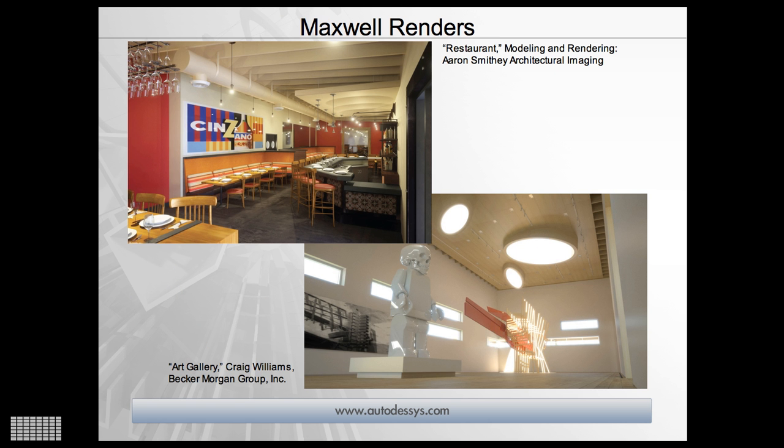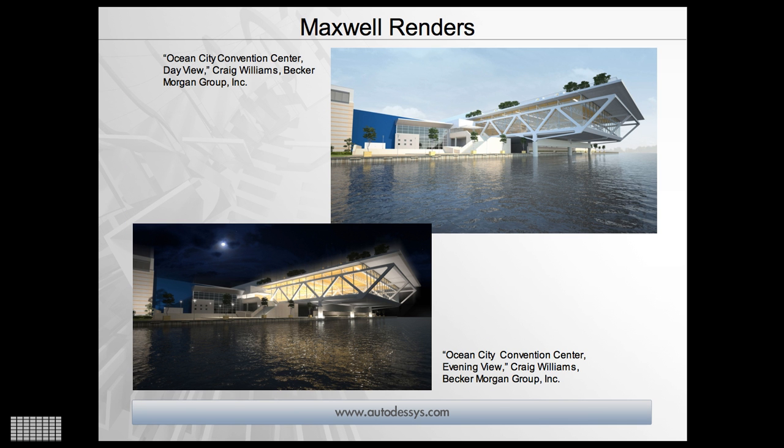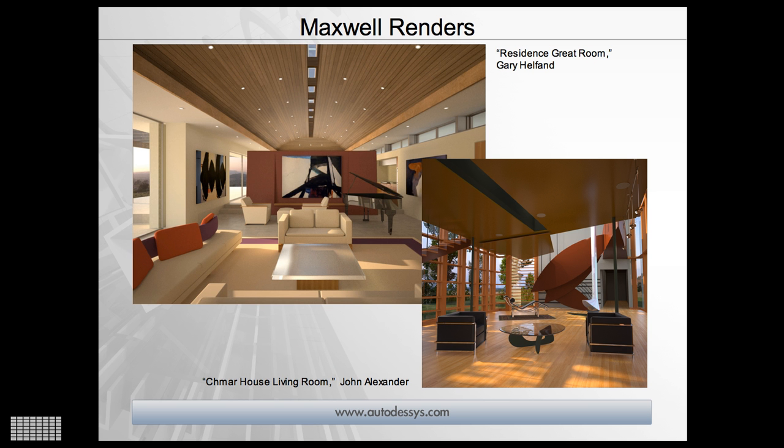Maxwell does work a bit differently than RenderZone, and while both produce images, Maxwell does it by calculating through all the equations that describe actual light and takes no shortcuts. Those equations we hated in physics class are now helping us out as we create amazingly realistic images. The technical term for this is unbiased, and it means in a nutshell that your rendered image will be just like you went and took a picture of your model.